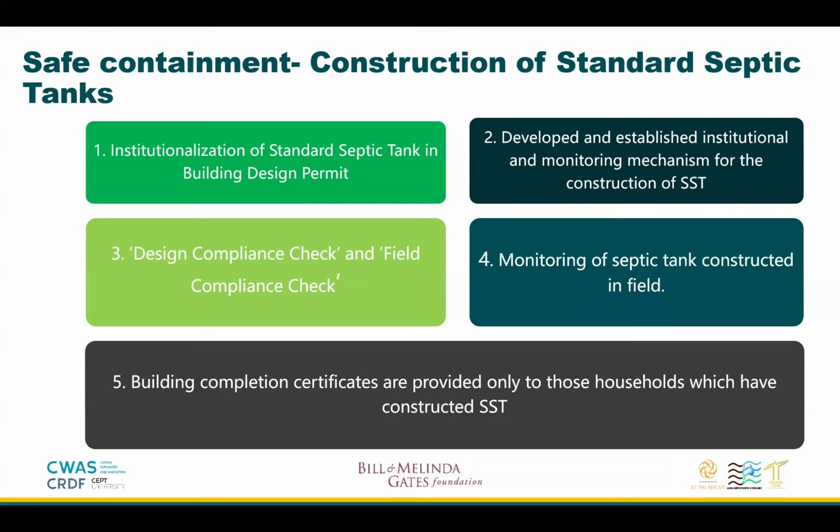That has been institutionalized within the municipality, and that has been possible with the institutional and monitoring mechanism developed by the municipality itself, which means the construction of the standard septic tanks is strictly monitored, and the compliance checks are done at two levels. One is at the design level, which means the designers should submit the standard septic tank design, and the other is at the field level, which means the responsible person from the municipality will go to the field and monitor whether the constructed septic tanks meet the standard or not. So if the compliance is met both at the design and at the construction level, only then are the building completion certificates provided to those households.